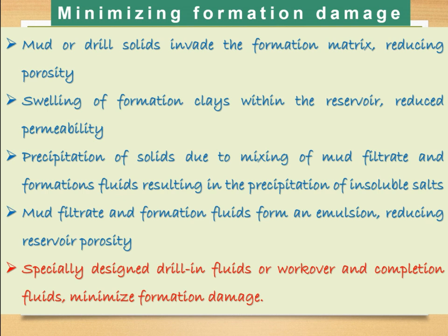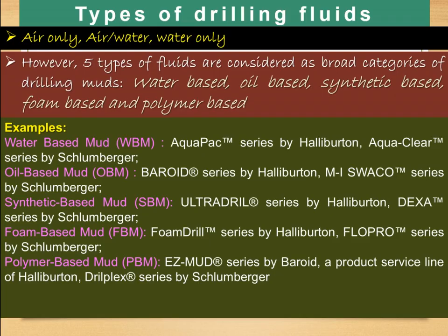Okay. Always drilling mud should be utilized judiciously because of precipitation of solids due to mixing of mud filtrate and the formation fluids, resulting in precipitation of insoluble salts, and the mud filtrate and formation fluids can form an emulsion, reducing the reservoir porosity. These are mostly problems encountered in oil exploration because porosity and permeability matter there. Specifically designed drill-in fluids or workover and completion fluids minimize the formation damage.